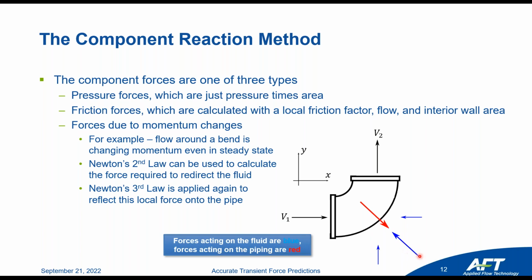So the fluid requires this force to the upper left. That means that there must be a force acting to the lower right on the pipe. And this is a kind of multi-dimensional case here. The forces that we are talking about, these elbow pair or longitudinal forces, might be acting only in the x direction here. So we really are only concerned with maybe this x component, and there would be a similar x component acting to the right on the pipe in red.